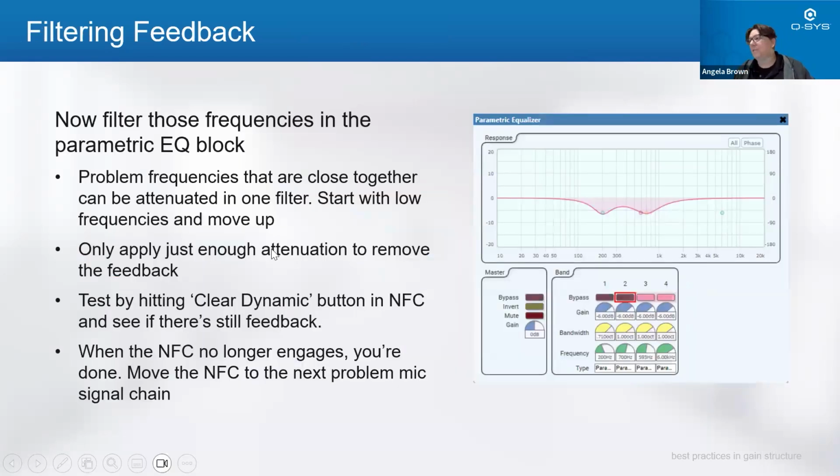Now I'm going to go into my parametric EQ and I'm going to remove them, and I'm going to remove them in a way that's much smoother. So a little bit less harsh, a little bit less of a situation where you've got these massive steep notches. Feedback filters are meant to be, I would say, a little brute force, because the whole idea is that they're active and live when a performance is going on. So they need to be instantaneous and dramatic. But when we're setting up a system in the beginning, we can hopefully eliminate some of that.